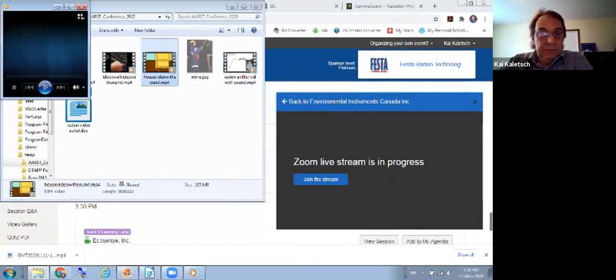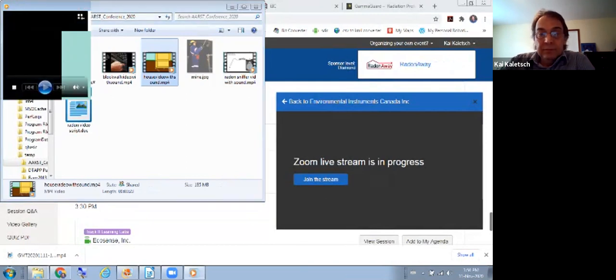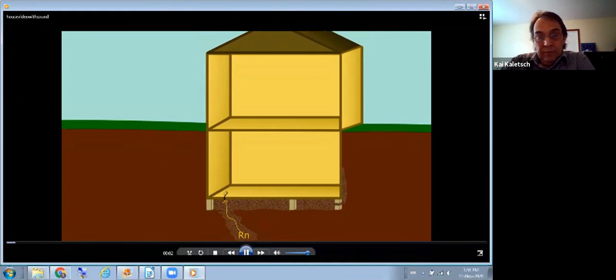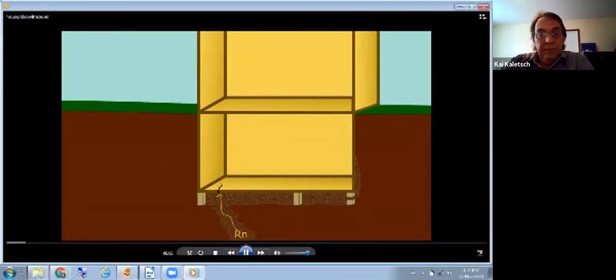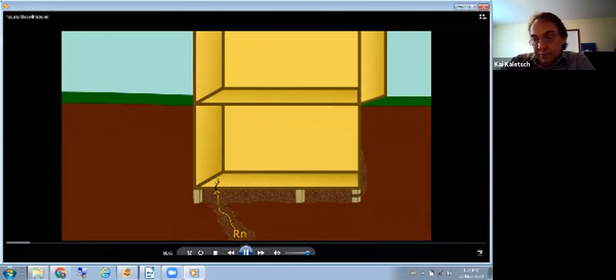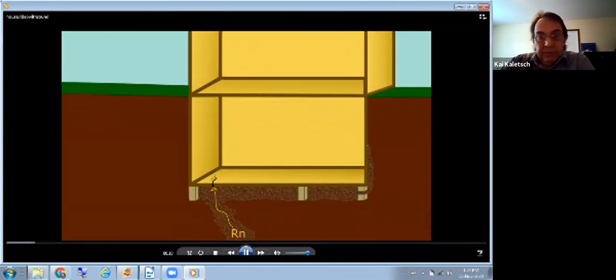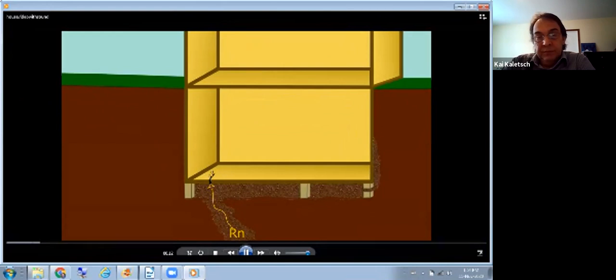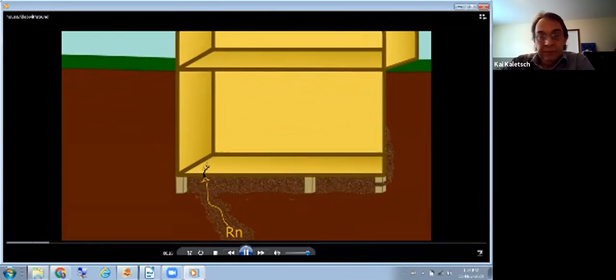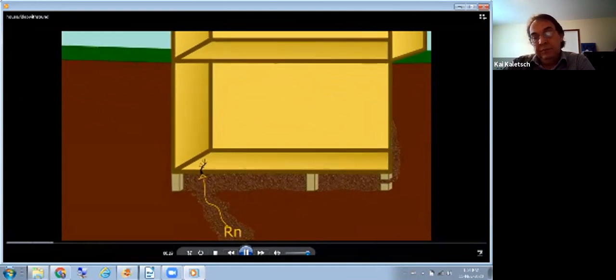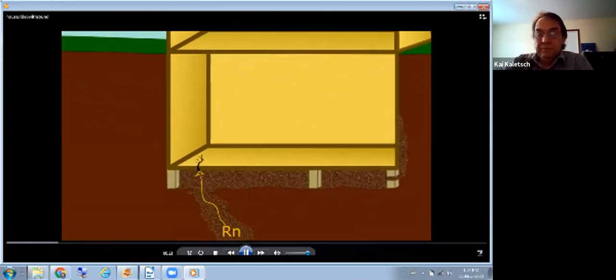Let's look at how radon enters a house. In this example, we have a fissure in the ground where radon comes up, a gravel layer underneath the house, and footings. The middle footing is a strip footing. The footing on the right has some penetrations and therefore is not airtight. Radon enters the house through openings, such as a crack in the basement slab.